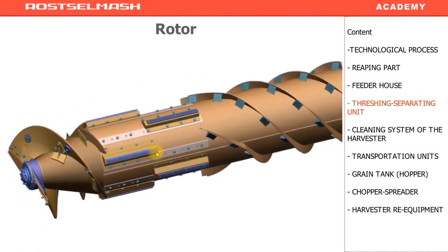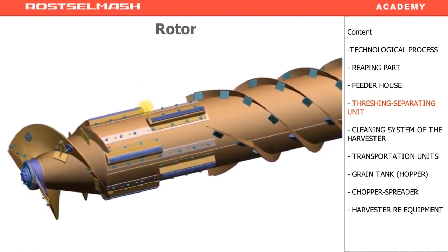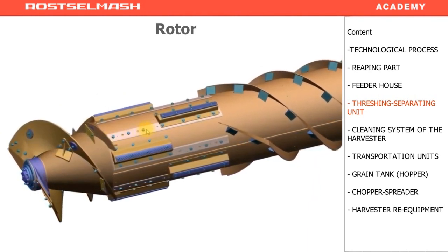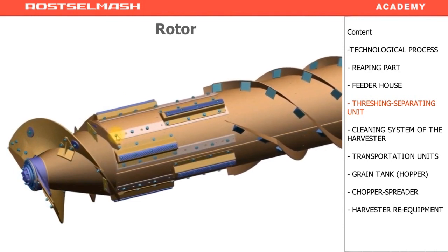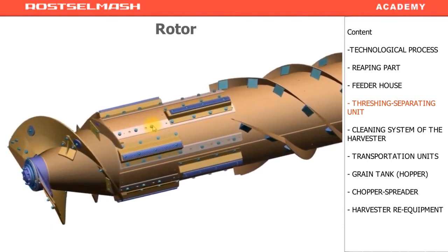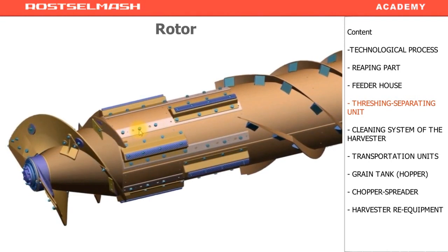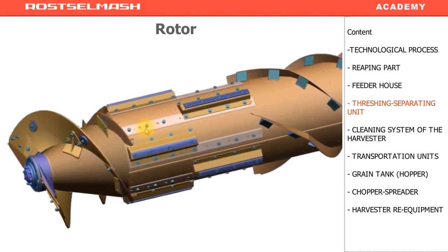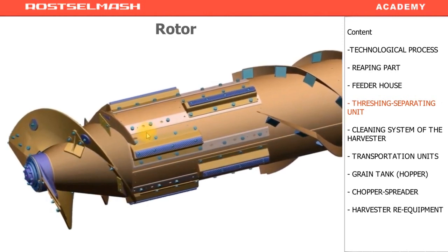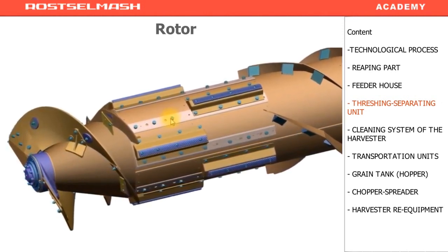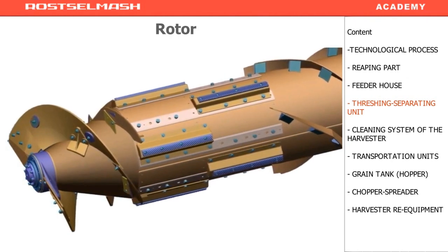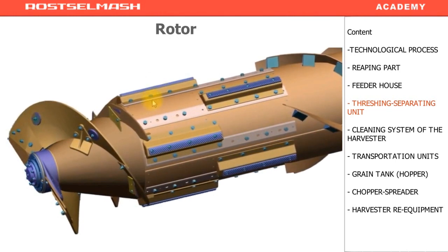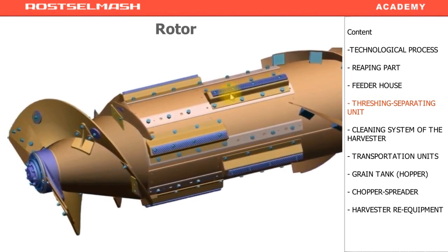The rotor has got rasps. In the photo, you see their positions. The other holes which are not used are plugged with bolts. On no circumstances should you unscrew these bolts, because during the harvester operation, there will be access to these holes. The inside of the rotor will be easily accessed and may be filled with chaff or straw. And during the operation, this compressed mass can cause disbalance, and this rotor disbalance will be very difficult to remove.